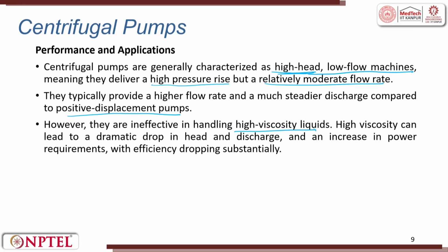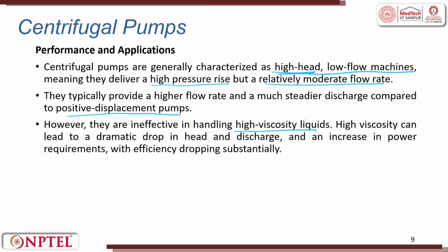Suppose tomorrow you replace the water with sugar solution, which is used in process industry or in pharma industry or in sauce industry, food industry, then high viscous fluids can be thought of. These fluids, oil, there these centrifugal pumps are not very efficient. High viscosity can lead to a dramatic drop in head and discharge and an increase in power requirement, with efficiency dropping substantially. So, for high viscous fluid, please do not use centrifugal pumps.